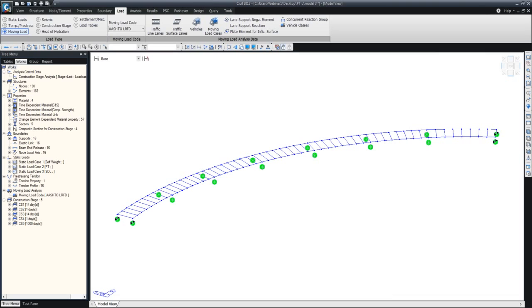Okay, there's another question coming in. If you have a deck and the lid slab, why do you need the dummy element? I think this dummy element is a misnomer. I apologize, I should have used another name, that is creating some sort of confusion. We call it a dummy element because it is not really in the physical world that you can see. It is just to replicate the transverse stiffness of the deck.